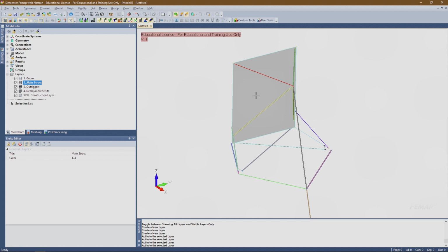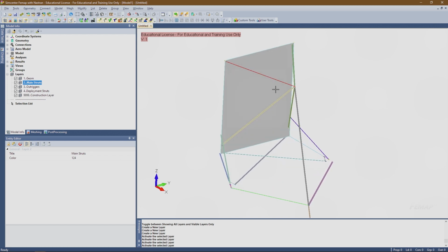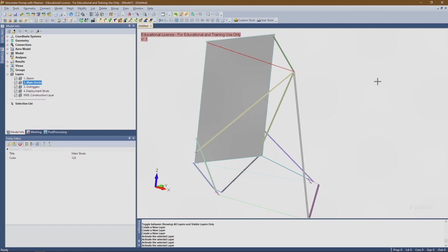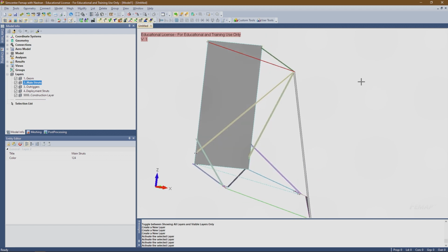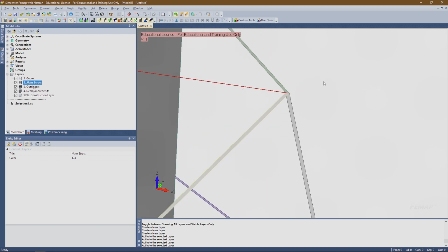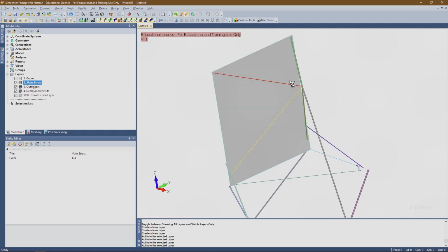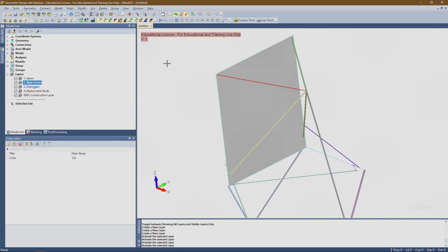It's all linked into the mesh of your part. FEMAP is not like that. You can literally grab a node and move it 10 inches away and make it a really skewed, ugly element if you want. I'll use direct manipulation of elements and nodes throughout the course of this video to set up all my constraints and whatnot, and you'll see that happening. So anyways, let's start with the outriggers, but